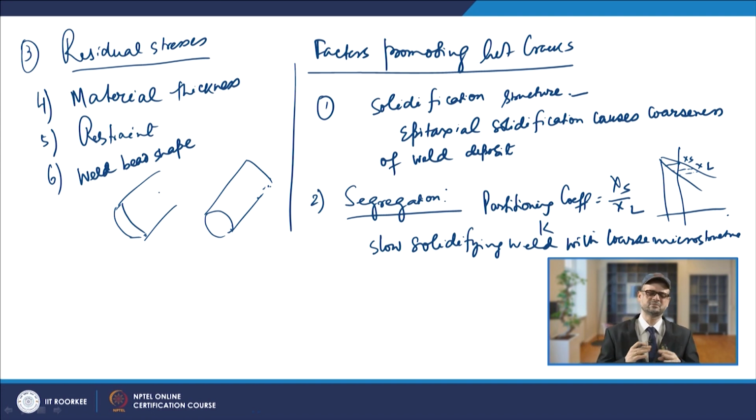But when you have a concave bead, when it cools and shrinks, the outer surface will be under tension, and then there may be cracks. On the contrary, with the convex bead you normally have very reduced shrinkage stresses in the surface area, and the possibility of cracks during cooling is smaller.